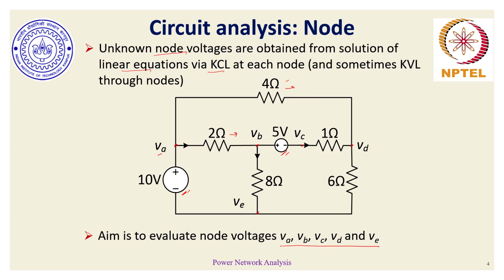We also have to understand that the node voltage, let's say VA, if we have to find its voltage, always is a form of potential difference. That means there have to be 2 points between which this voltage or potential can be measured. So in this given circuit, if we have to find these 5 unique voltages, we have to choose a reference for measuring these voltages first.